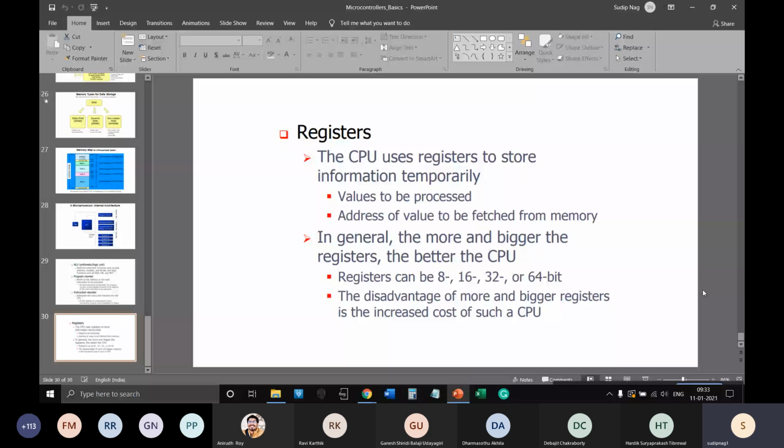That's not always true. Exactly 5 volt is not possible. So you can maintain anywhere between 4 volt to 5.5 volt, for example. So 4 volt to 5.5, a 1.5 volt range around 5 volt, is considered to be logic 1. So those exact voltages could be 4.5, that could be 4.8, all those things. So those are analog voltages. That means your transistors should be either in saturation or cutoff given that range of voltages is applied. So that means any digital circuit is analog in nature.